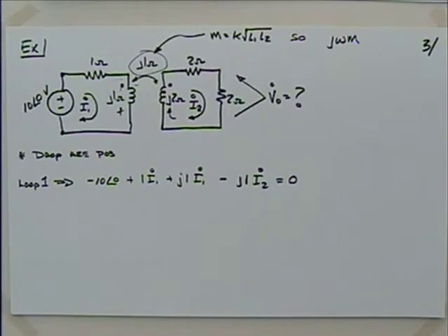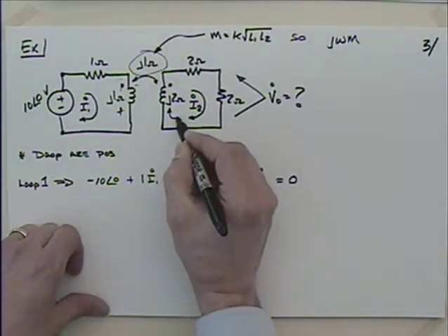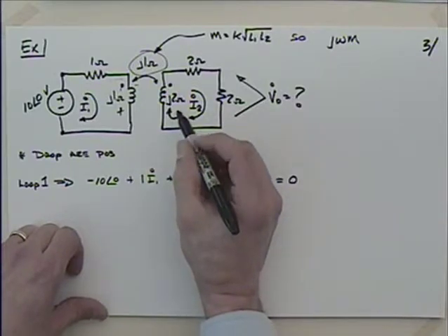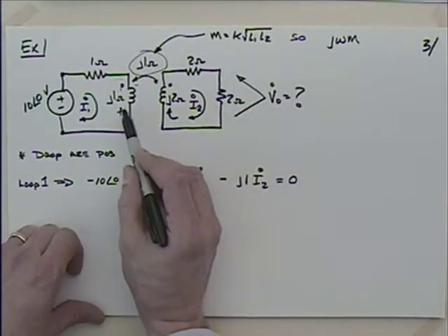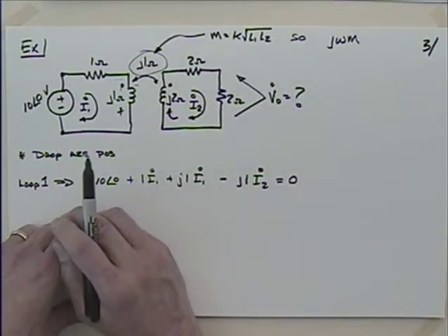So is it negative when it's going into the j2 ohm inductor? Is that entering negative by observation that the other is positive? Well, it enters the terminal that does not have the dot. Okay, so now I come over here and I say the terminal that does not have the dot has to become positive.